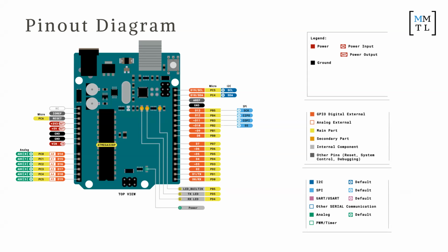These here indicate that these are digital pins, right? The tilde indicates that it's capable of PWM. And then these ones here indicate that it's analog. Okay, so this is a sort of common diagram. If you end up ever doing anything mechatronics, you need to be able to read what's called a pinout diagram. And there's a color coding, an explanation of what each color means here. Okay.